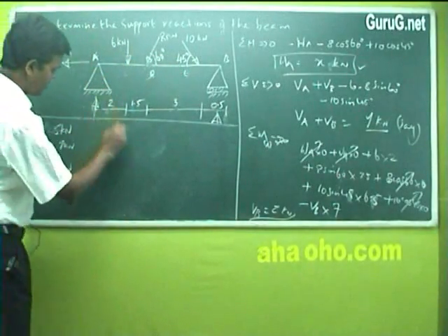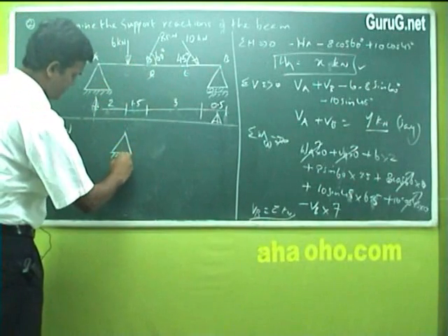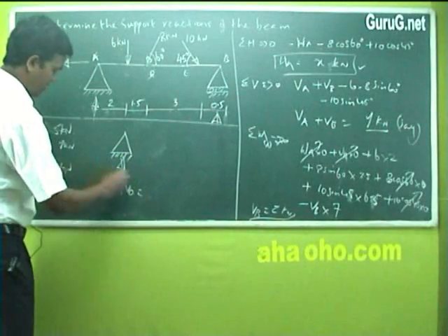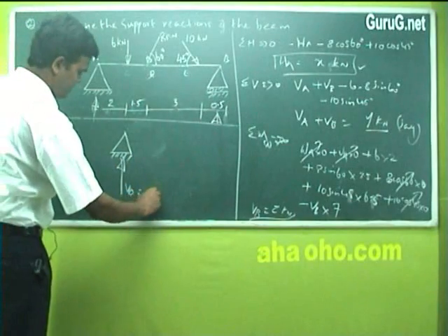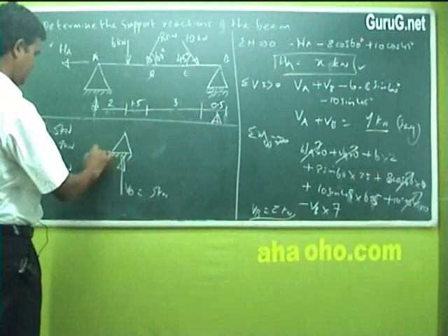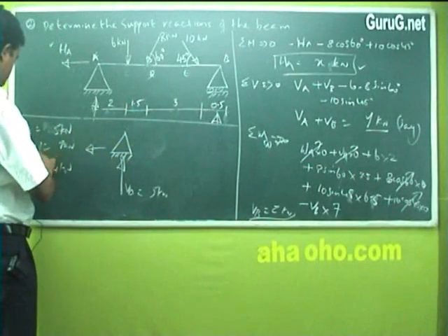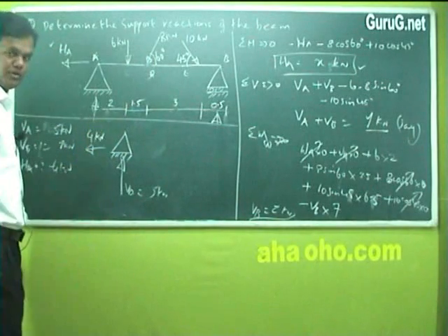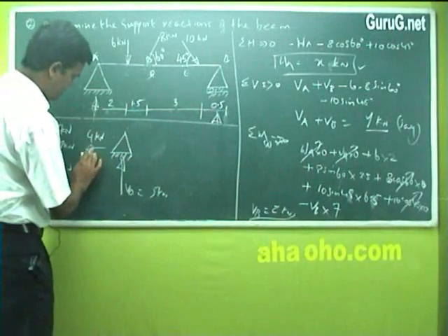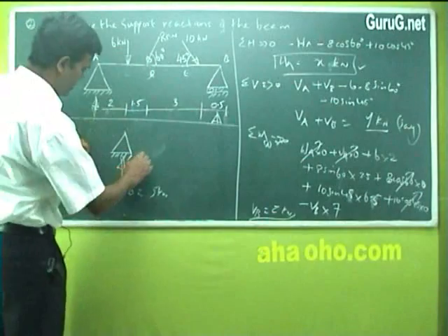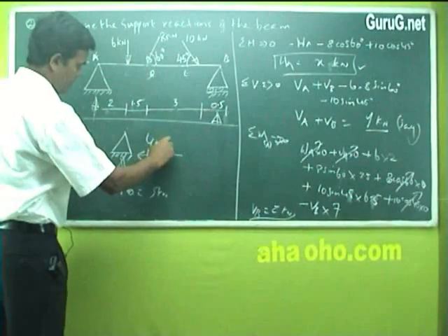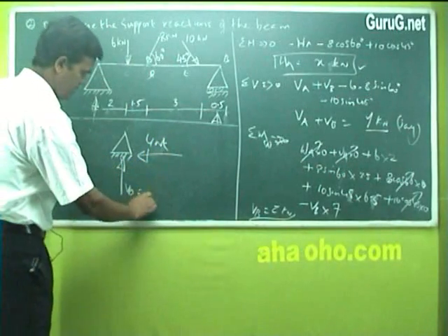Now what you have to do, the hinge support is this, you have to draw a sketch. Hinge support, fine, this is VA. You got some value here, suppose I just take an example of 5 kilonewton, and HA will be some value in some direction, say 4 kilonewton, both positive, right? Now where will the resultant be? Instead of writing the arrow mark here, I'll write it here, because anyhow it is going to the left-hand side. I'll write 4 kilonewton. VA is 5 kilonewton.